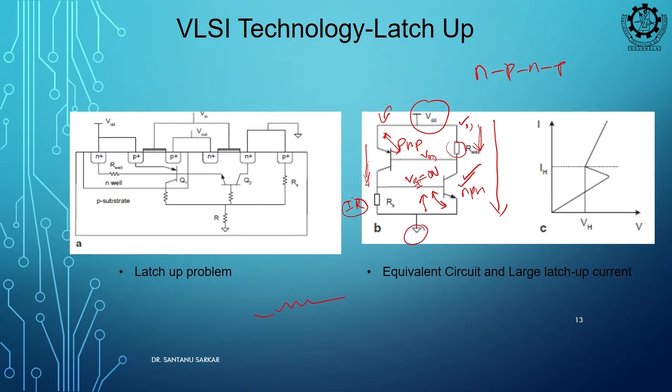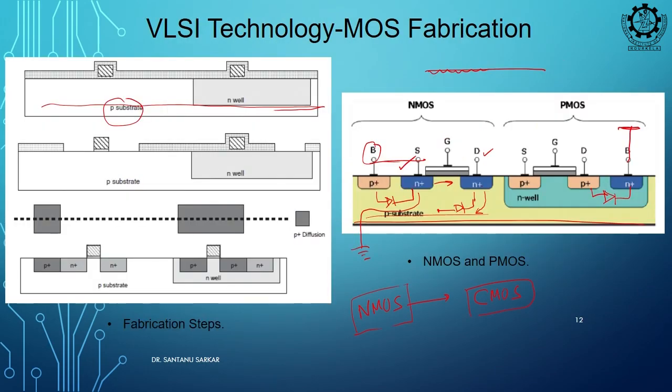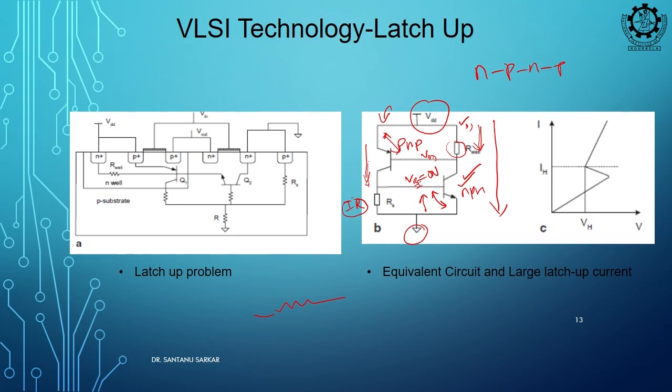You told that there will be some reverse bias current, right, leakage current. So, due to that leakage current some IR drop will be there. If that IR drop grows and is greater than your VB on, this will turn on one NPN transistor, this NPN transistor will in return turn on this PNP transistor, and in this structure one is turning on the other more strongly.